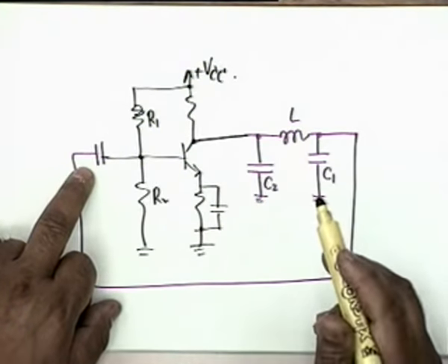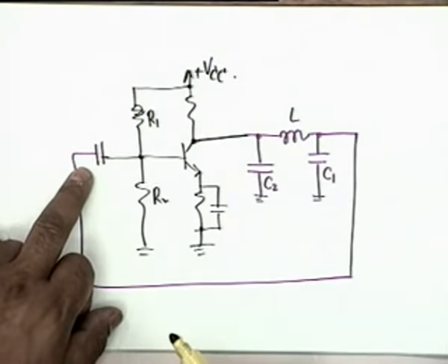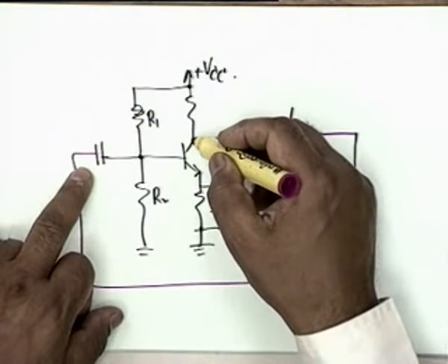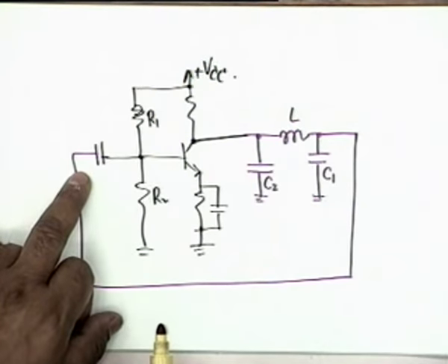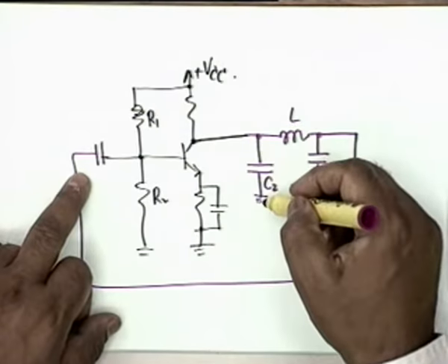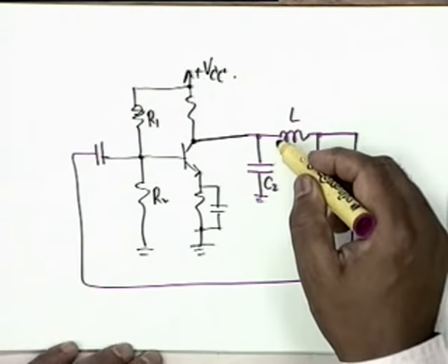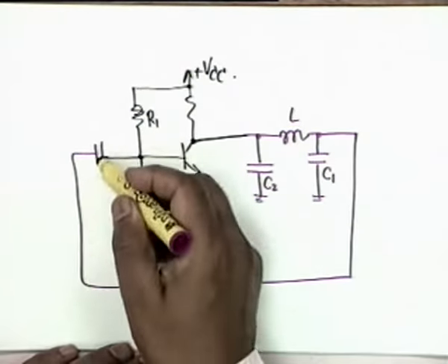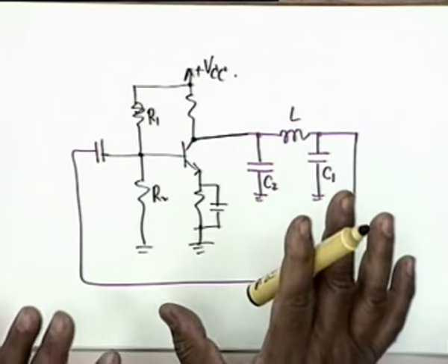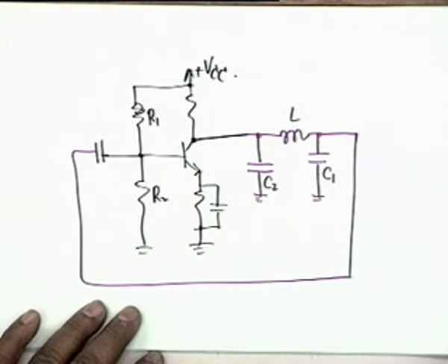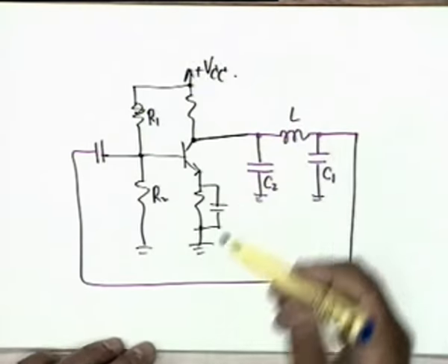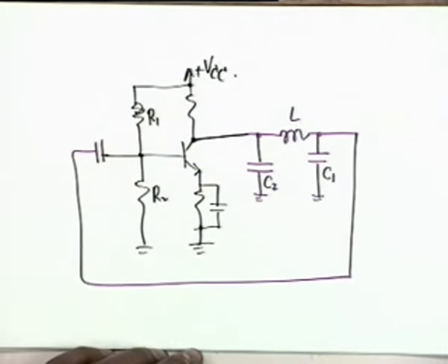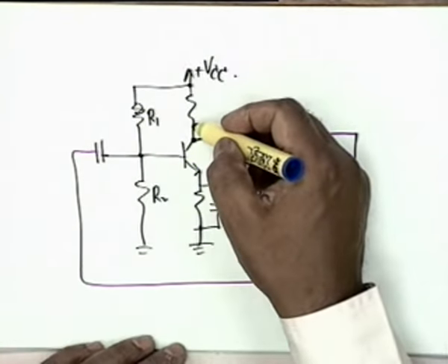If it is, that's okay, but there is a DC here. There is a DC voltage VCE here, which will appear across this capacitance. No problem. The inductor cannot pass DC because of this capacitor. So this is a good circuit. In a practical circuit, we don't want to unnecessarily waste power, and this resistance is not an absolute need.